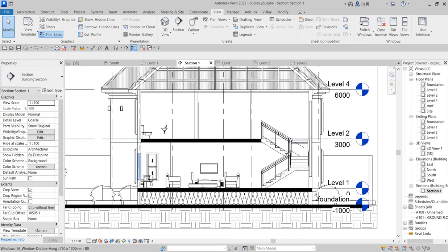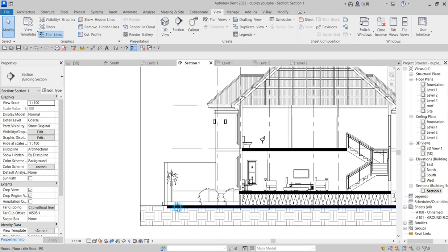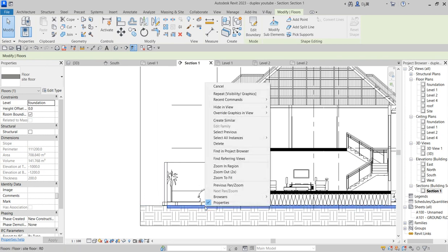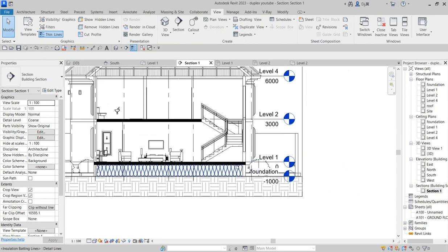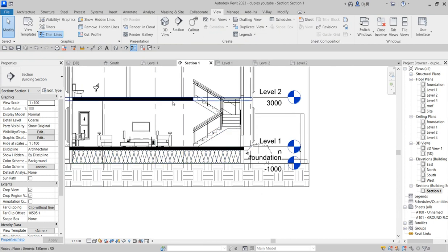The same thing, because you use floor, you use ground floor to do this, so it has the same thing. So everything that is contained in that floor is what you use. So like this below one, what you can do is that you, from this view, you hide the element. So you'll be able to maintain this for the remaining one and that for this aspect.